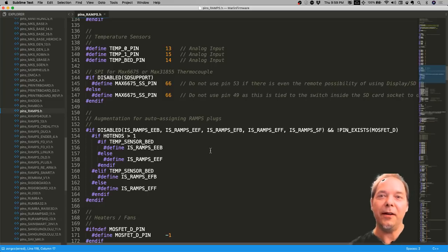voltage or a resistance value as a proportion, usually between something like 0 and 255. An analog input will look at the resistance, and if it's 100% resistance, completely resistant, it'll be one value, and at the other end where there's no resistance, it'll be the other extreme. And at 50%, it'll be 128. These pins are numbered that way, so they don't actually correspond to digital pin numbers at all. There may be digital pin numbers that correspond to them when you're doing digital I/O with those pins, but you'd use different numbers when you're talking about digital pins than when you're talking about analog pins. So a little background.